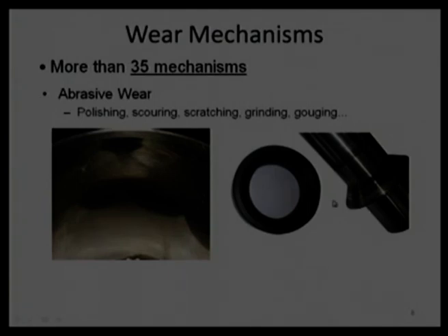What we are saying is that let carbon graphite transfer its layer on the stainless steel, because adhesion between stainless steel and carbon graphite is higher compared to cohesion between graphite and graphite. So, a weak interface will be made between graphite and graphite surface, but good adhesion will be made between the carbon graphite and stainless steel.